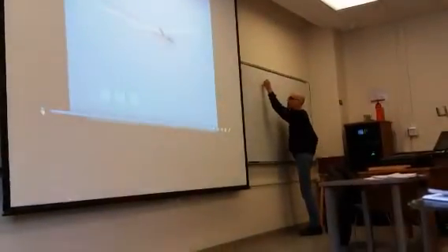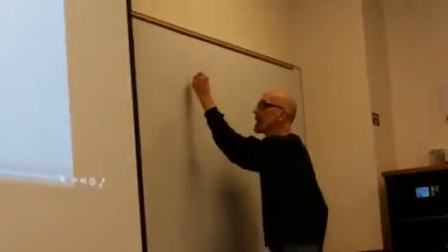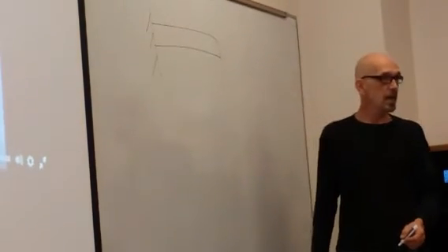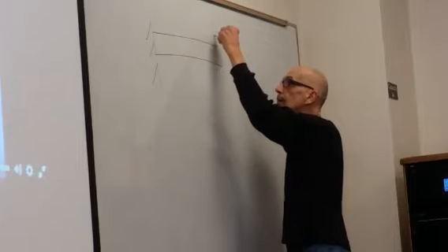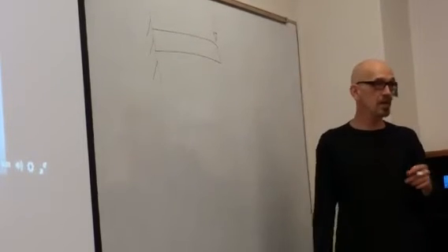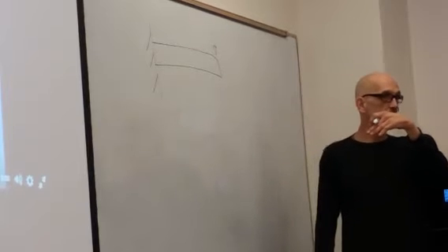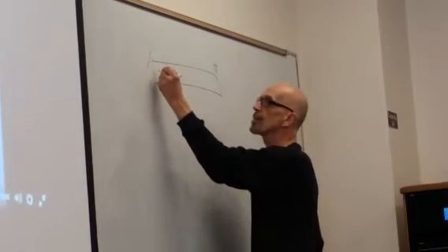So the idea here with this thing is in the framework, a simple model for this. That's the fuselage. You got the cantilevered beam, right? Okay. Now the first mode, if this thing is excited out here, which oftentimes it is due to the aerodynamics, right? You got the flow around the tip of the wing. So what happens if it's excited here is this is the fundamental mode.